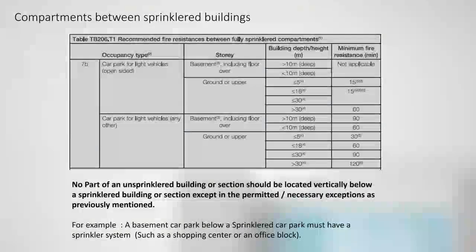Right, so as I say, for example, a basement car park below a sprinklered car park must have a sprinkler system, such as a shopping centre or an office block. So when the fire engineer's putting that together, he's got to take that into account. Otherwise, you're going to end up with a non-compliant sprinkler system, etc., etc.